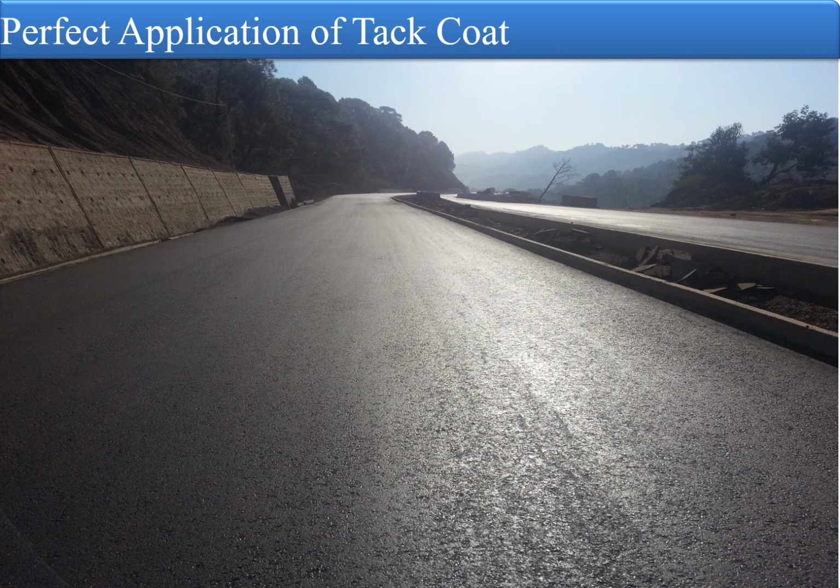So this is the photograph which indicates, in my opinion, the perfect application of tack coat, which is smooth, uniform, and has perfect tackiness, ready to receive the new HMA layer.